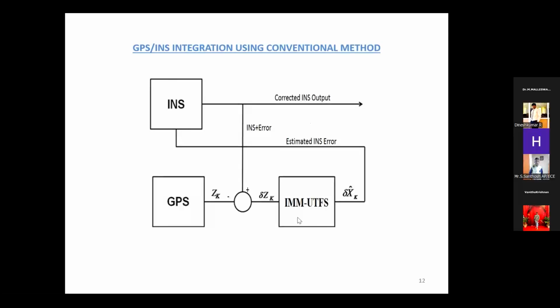And the next drawback is that whenever you give inputs, especially latitude, longitude, and in the case of air vehicles, altitude values, the mapping of the input values becomes very crucial. It also requires a lot of complexity in updating your measurement noise and process noise, right?